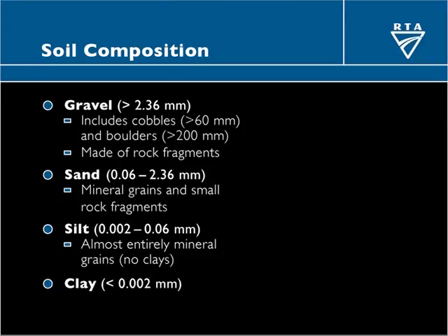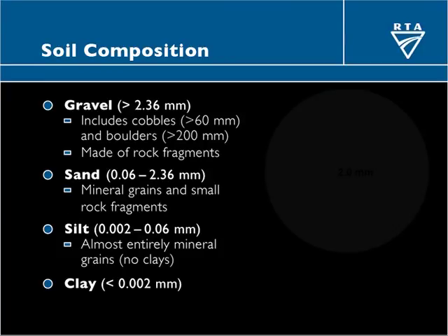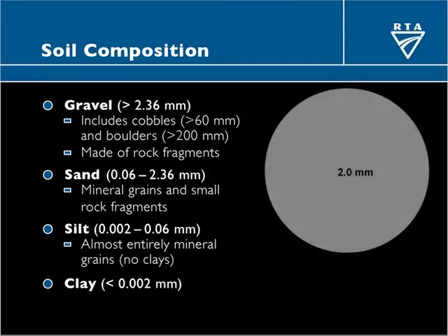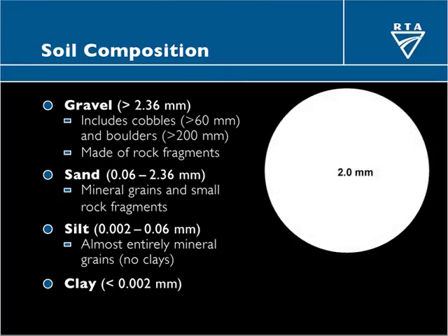Clay is even smaller than that, down to well below microscopic size. Now, to give you an idea of the relative size ranges, we've got a small illustration, which you can see here. The big one is about the biggest size of sand grain, a couple of millimetres across. If you went up from that, the smallest cobble at 60 millimetres